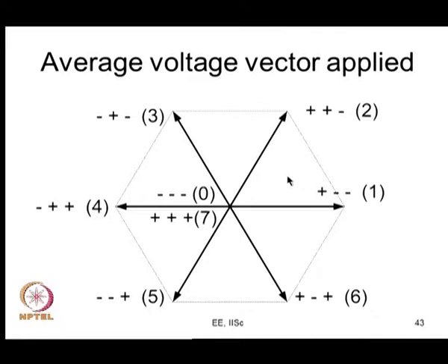So, if I look at the voltage vectors, what happens now? I might come to slightly higher modulation indices. Like this. You can very evidently see that if I call this Vref 1 and I call this Vref 4, their magnitudes are very, very different.